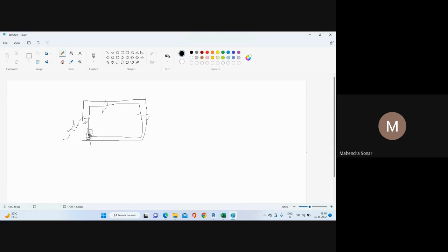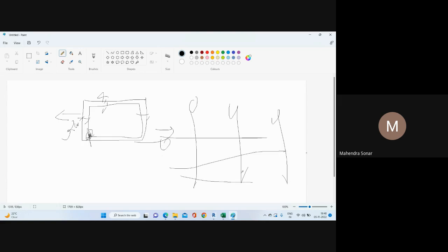The thickness increases outside, so my point is not disturbed. So generally the project point is the lower bottom internal corner of the wall. But in our case we are just starting this grid, so you can give any as per requirement. I want to give here because this point is my fixed point. If I want to add one more grid, I can't give the left bottom. But this point should be the same for all disciplines.